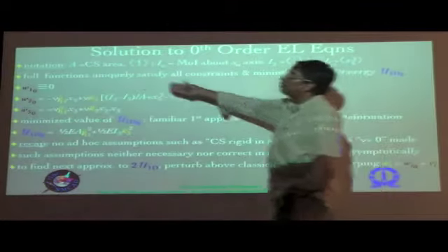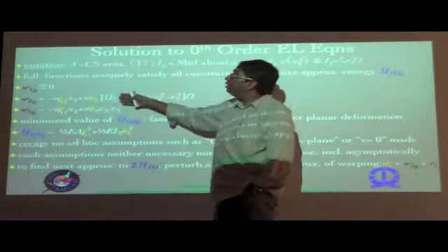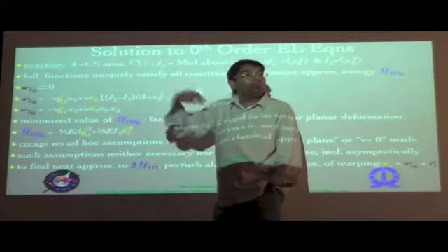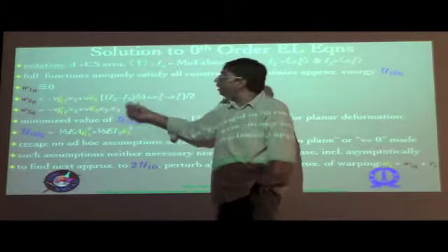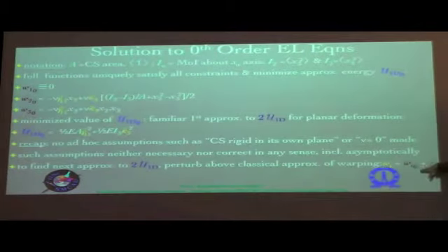We already got a particular solution to the warping. This is a leading order solution. The actual W is a little more refined than this, and may contain higher order terms. So what we do is, to that Wi naught, that is i equal to 1, 2, 3, the zeroth order approximation, we add a perturbation term Vi, so that your warping Wi is given by the sum of those two: whatever solution we have already got, and the perturbation which we want to determine, in terms of Wi naught.